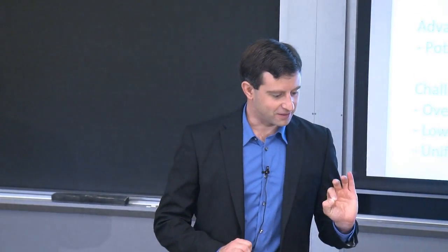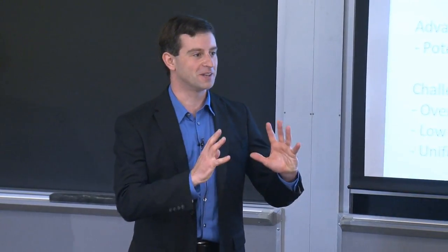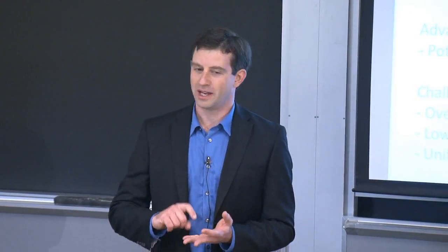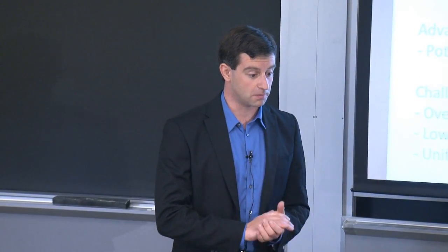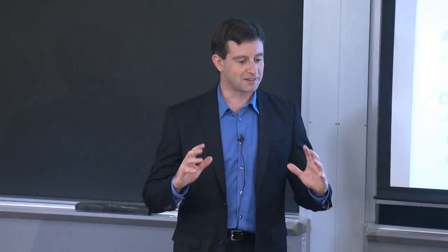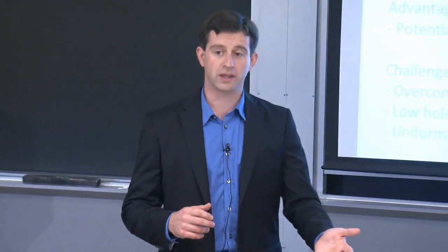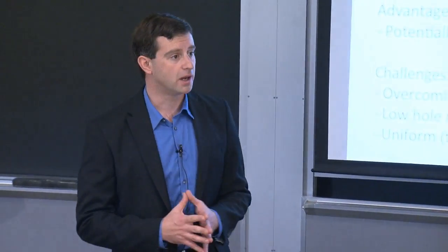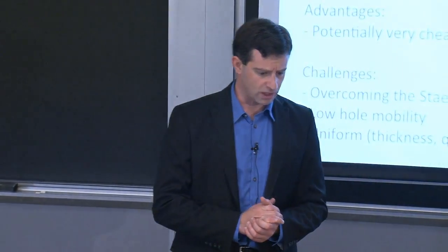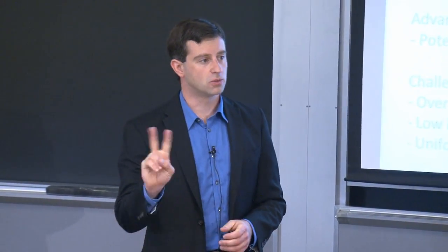And the reality is that with any amorphous material, you can deposit a range of materials. It isn't just one specific amorphous silicon material that you get every time. Depending on your deposition conditions, depending on the pressure and the temperature and the power during the PECVD, the plasma enhanced chemical vapor deposition, you obtain a range of amorphous silicon materials. And within that range, you can find that the mobility of charge carriers can vary by several factors. The mobility, I believe, in amorphous silicon can range easily between 0.001 and 0.1 centimeters squared per volt second. So that's 2 orders of magnitude easily.